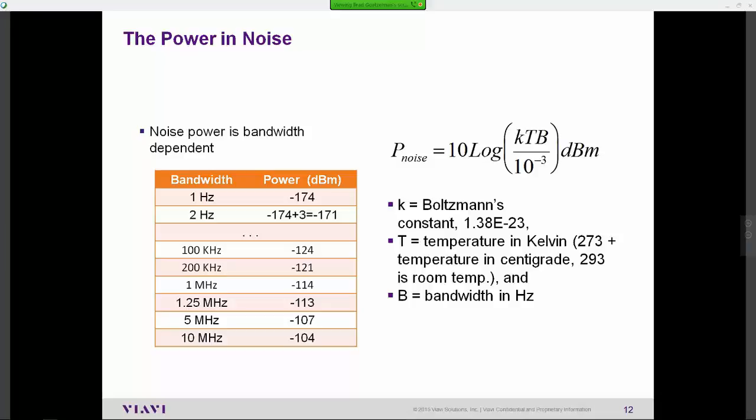You cannot get any lower than this. Now, you will have values, and you'll see in some of our slides, that you actually have to add a little bit more to this because there's always a noise figure, which oftentimes is part of the system. But needless to say, this is probably one of the single most important slides for understanding and finding interference by understanding exactly where your noise floor is using Boltzmann's constant, or that KTB equation.